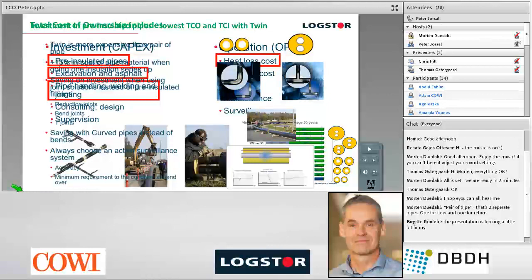If you go one installation series up, for example from CS1 to CS2, then you'll have a 2% increase in the installation cost. And again, you will have a saving on doing joint solutions on bends and tees instead of doing the pre-insulated solution with fittings and straight joints.